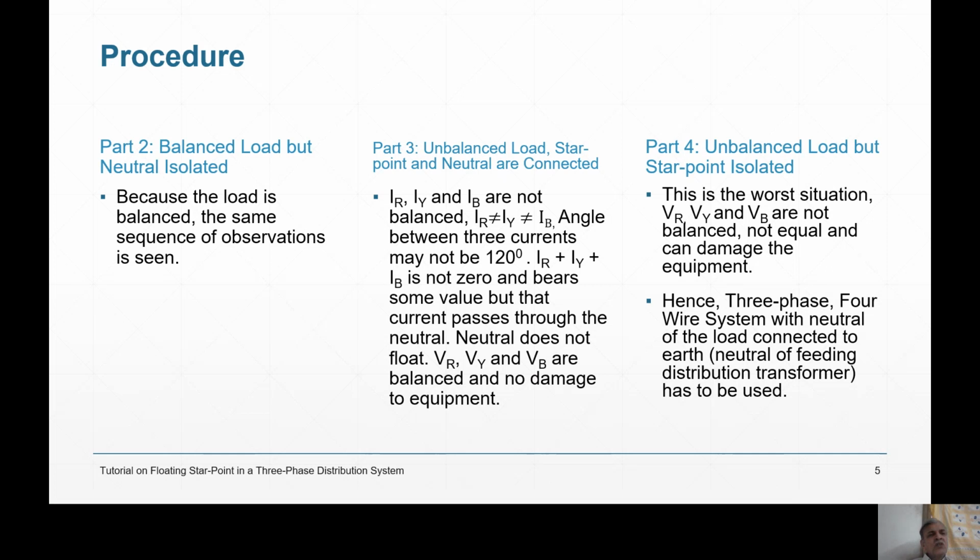Because of under voltage also the equipment will be damaged. Particularly the induction motor will be damaged because it was taking some power. It is taking the same power yet because mechanical power does not change. V I cos phi is the same. And because V has reduced, I has to increase. And increased current will damage the induction motor. Therefore, low voltage also would damage.